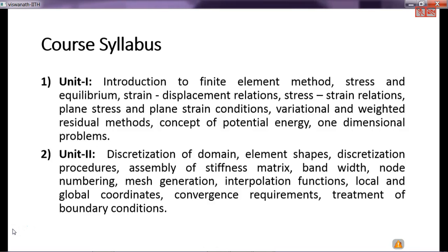Now, what you're doing in the finite element method is you are still writing the equilibrium equation, which is the governing differential equation, but in a discrete sense. So it's like saying welcome, namaste, or bagunnara in different languages. But the meaning of it is that you are welcoming somebody, right? Similarly, you're writing equilibrium, but we cannot solve the equilibrium equation in strong form. Weak form is like an intermediate form; unless you write that, you cannot go into the discretized equilibrium.